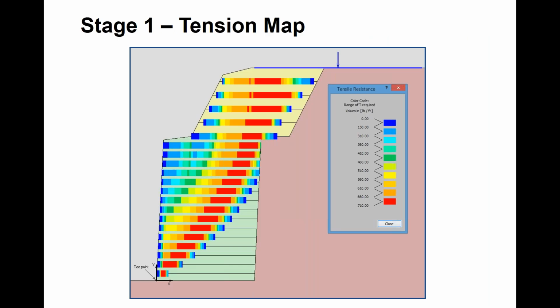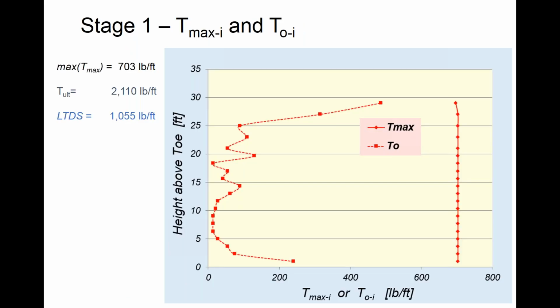Note that we do have a red band, that swath of maximum tensions. However, the maximum point doesn't lie on one surface, and in fact, it contracts and expands based on backfill geometry. There's also other local maximums occurring here. There's no other way to capture this kind of mechanism and this kind of visualization of reinforcement demands.